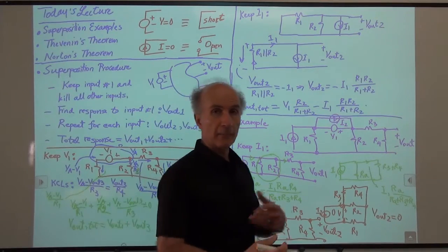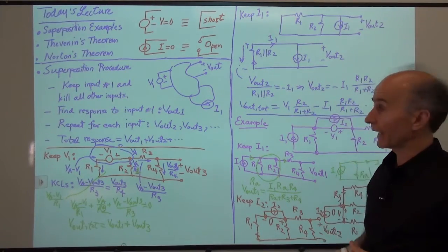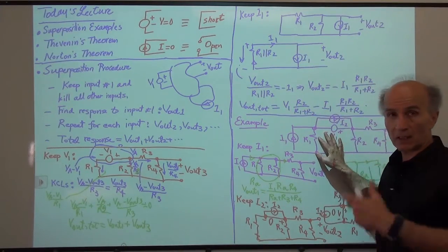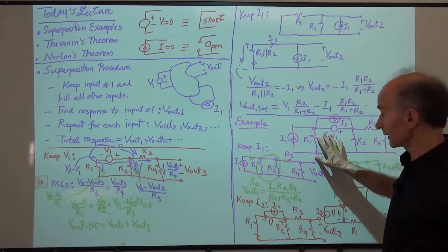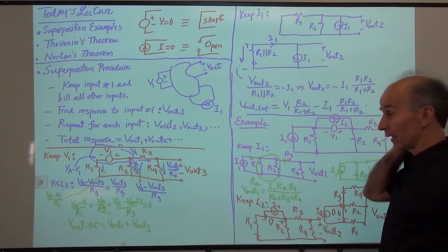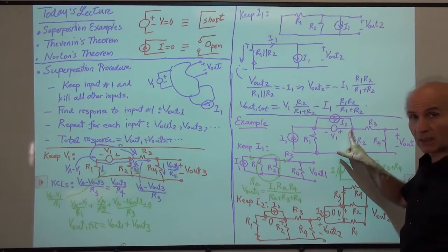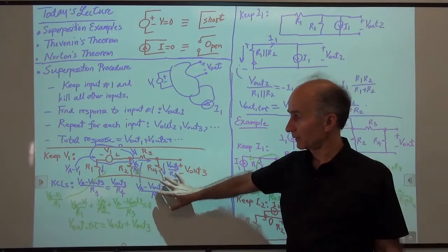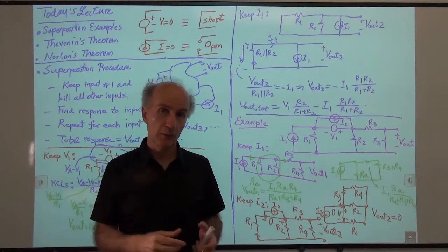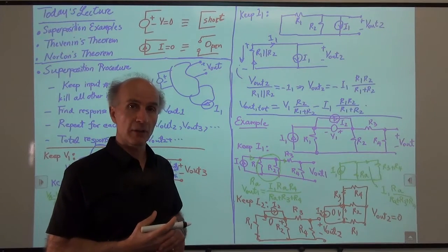Okay, so you see, these are the mechanics of superposition in order to analyze the circuit. Again, you might ask, is this really simpler than treating the circuit with what we know before, like node analysis, right? Can I just write node analysis here? Yes, and in fact, that might be even a little faster than what we did here. We would have a super node here, and we would have only one voltage here, one voltage here. So that would be actually similar to the work that we did in this last part. So whether superposition is helpful or not depends on the actual circuit we are dealing with, but it's a very nice tool to have in our library of techniques.